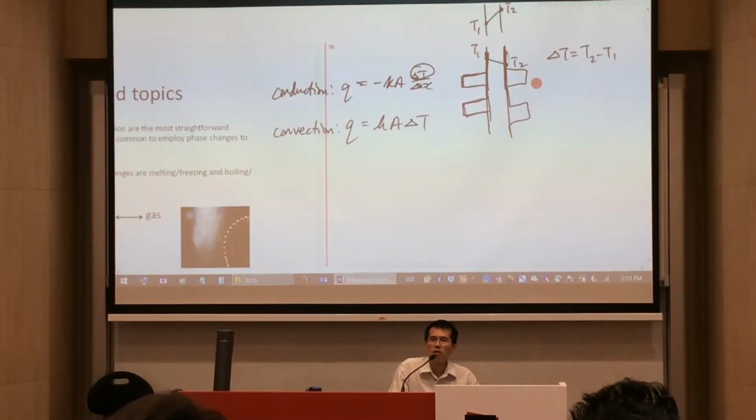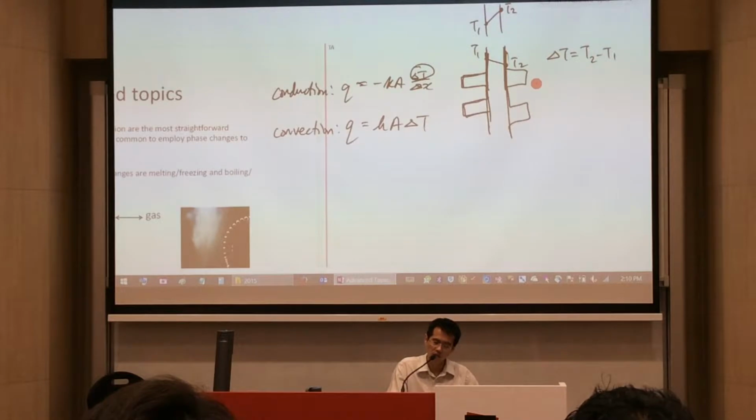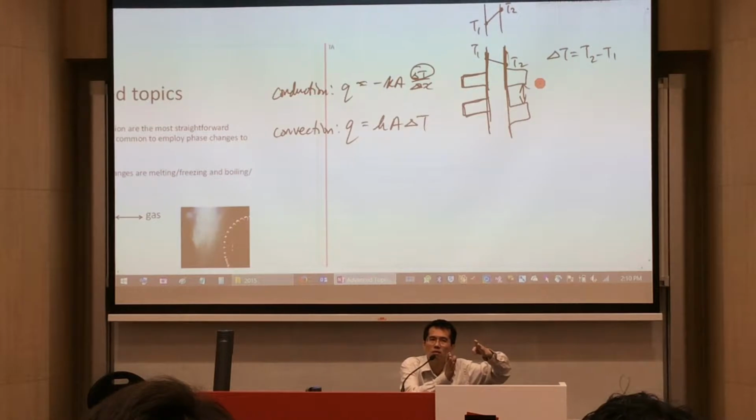Now, although we said that we could increase the surface area using fins so that more heat is transferred, really there's a limit to this surface area by introducing fins. There are things that play into how effective fins would be, like interfin distance. If it's too close, then it's not so effective.